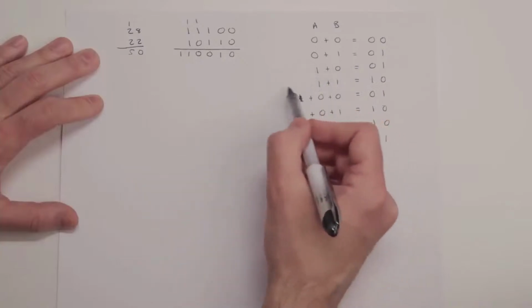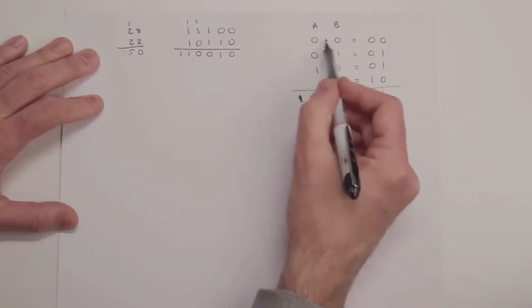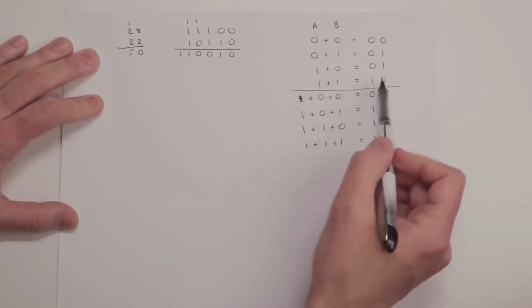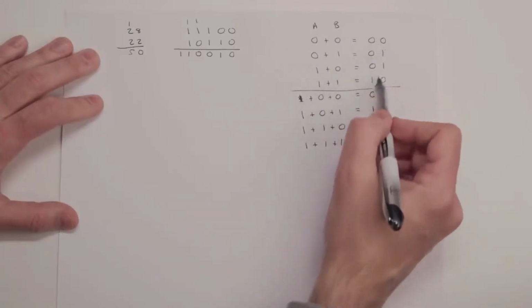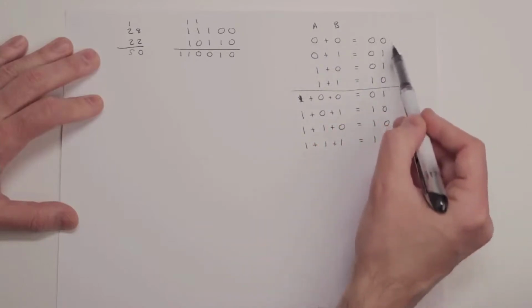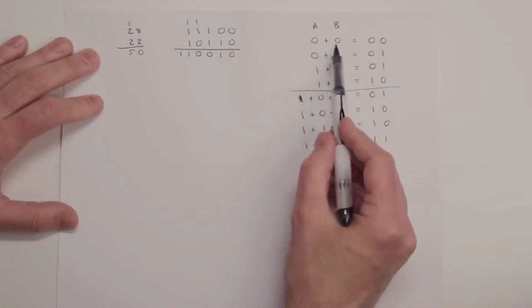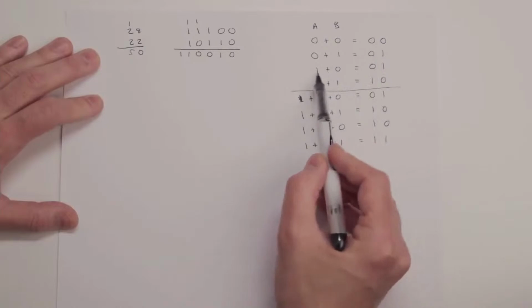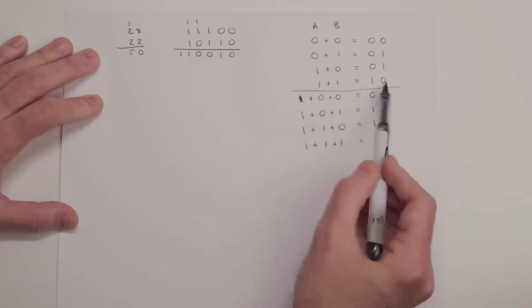So if we look just at the case here where we've got two numbers that we're adding, so we haven't carried something in from a previous column, and we look just at the number that we're putting down at the bottom here, this actually looks a lot like an exclusive OR, right? Because if A or B is a 1, then this last bit here is a 1. If A or B is a 1, but not both.